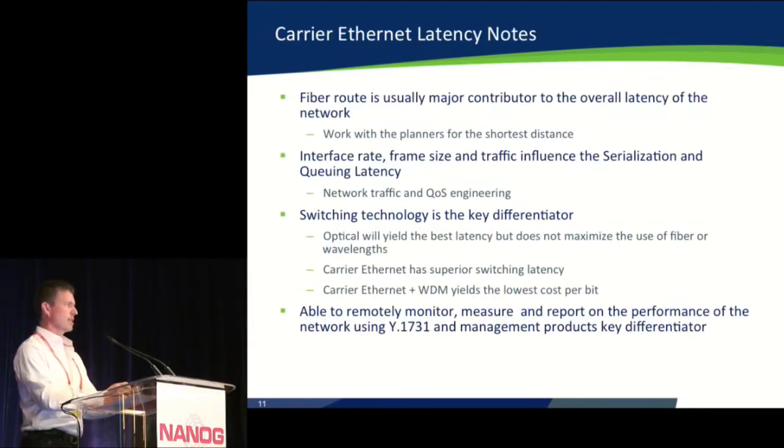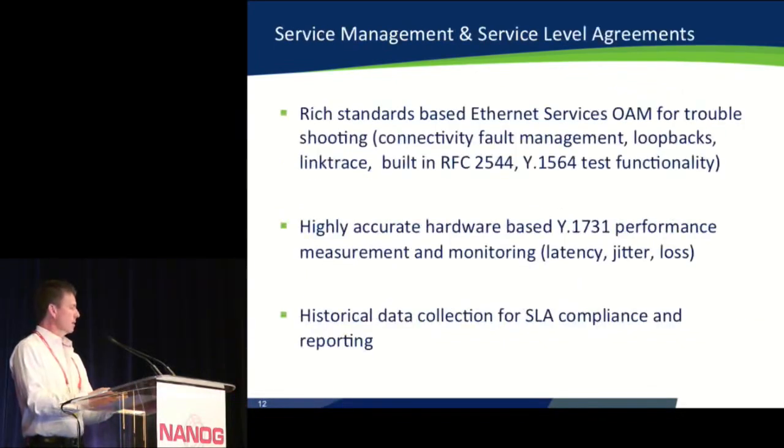And then, of course, the switching technology is a key differentiator in the sense that with packets, you're not buffering a full frame, you're switching at the packet level. So the latency through the switch is much, much less. And so we also have to be able to monitor all of these, this component as well as others. And service management and SLAs are a big part of carrier Ethernet.